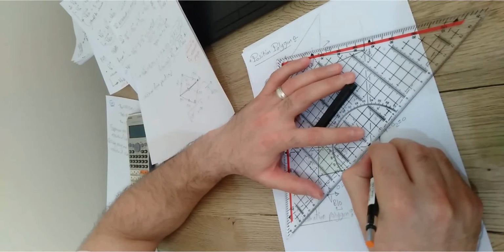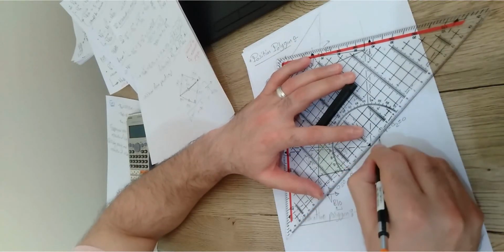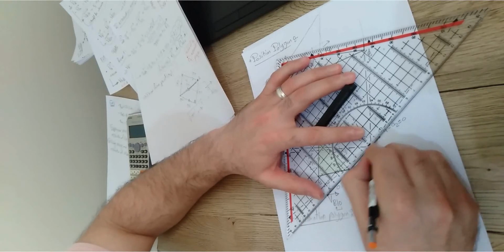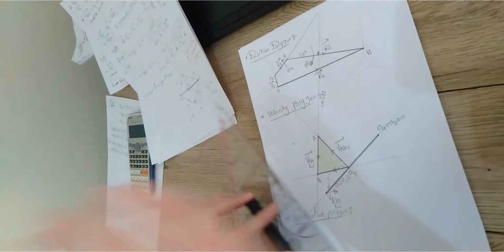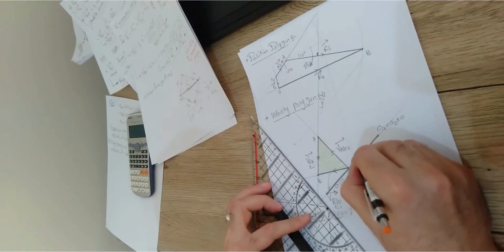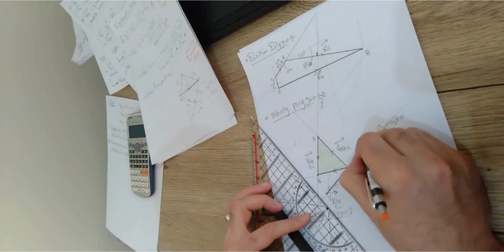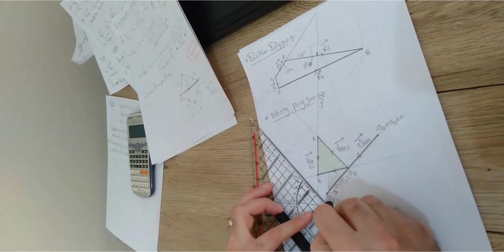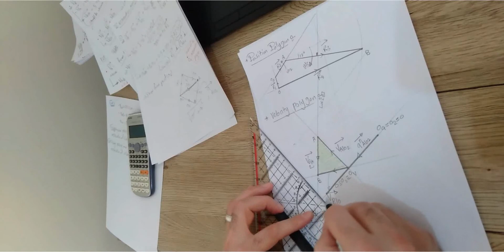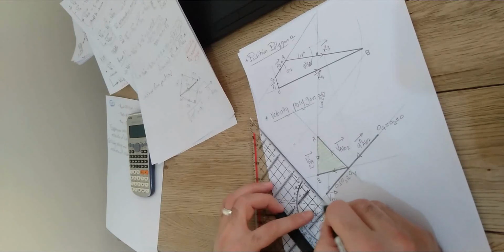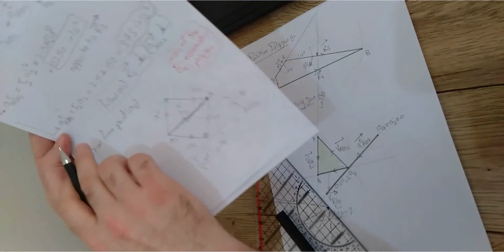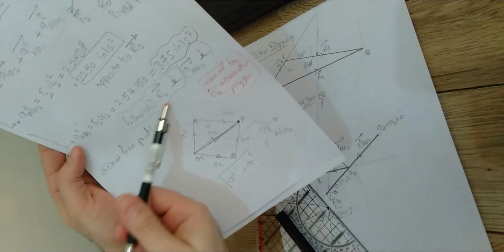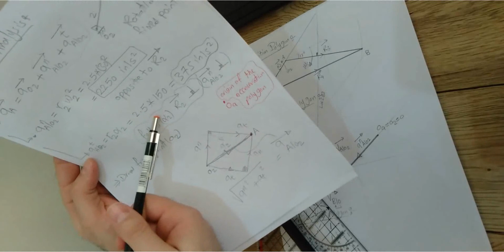So if I draw a line, this line, I'm going to make it a very thick line, just to distinguish this line from any other line of the velocity diagram. So this component should be the A normal of A relative to O2 vector, right? And from the end of the normal, keep going. This point is not point A. You still have to keep going, because we still have another component, which is the tangential component, that should be perpendicular to the R2, following the direction of alpha 2.